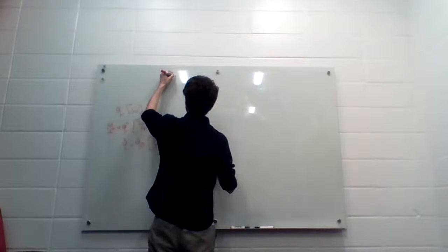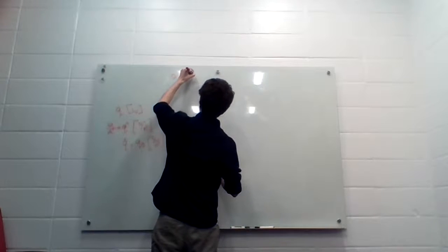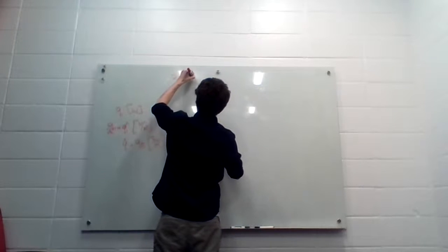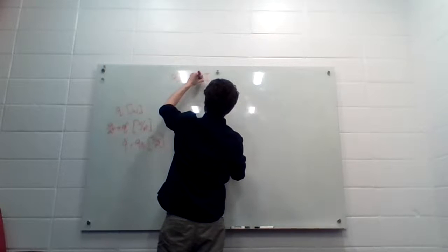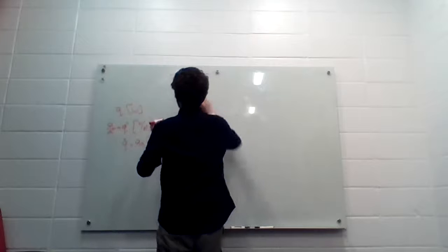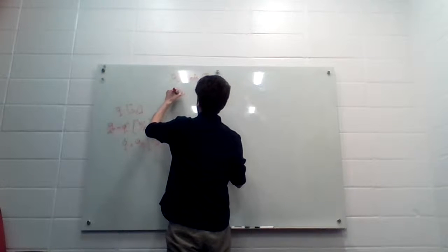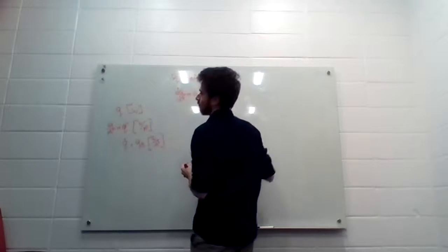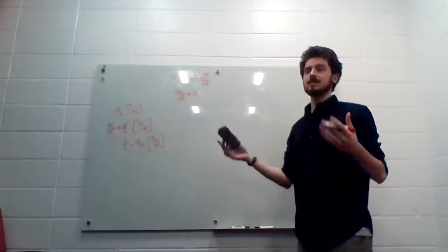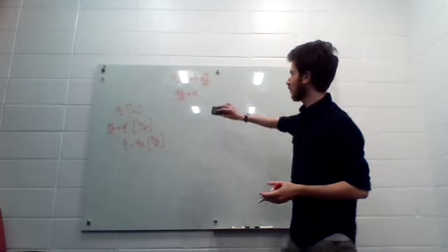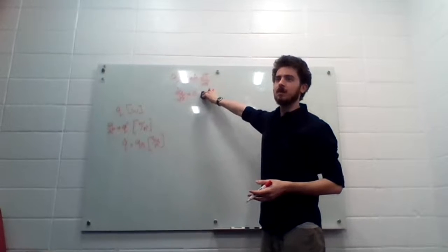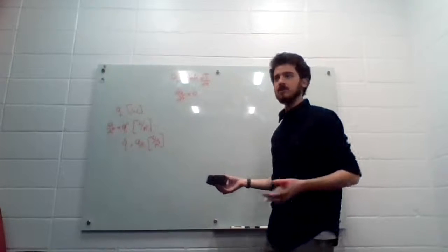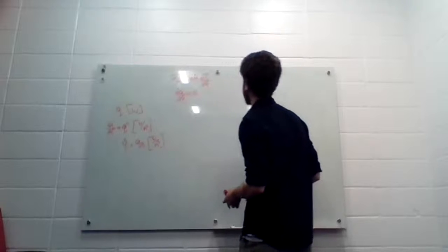So we know empirically, negative, actually, sorry, it's negative kA dT dx. So that's your empirical observation, and then we know for our generic thin slab problem, really any slab problem, dq dx equals 0, as long as there's no heat generation. And by the way, in the homeworks, when we say things like state your assumptions, these are exactly the things you want to be mentioning. You want to really drill down: this is predicated on no thermal heat generation. This is just empirical. Something else is predicated on the first law. Well, this is predicated on the first law plus no thermal heat generation.